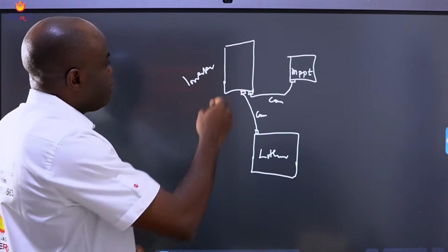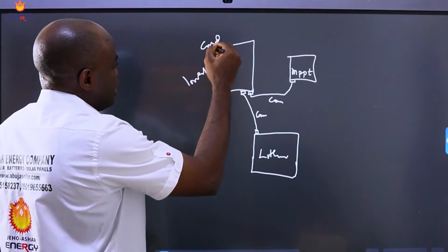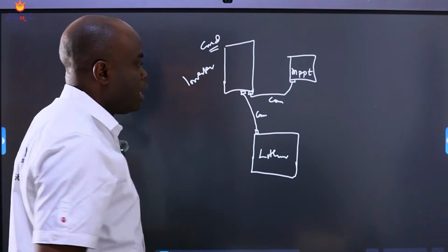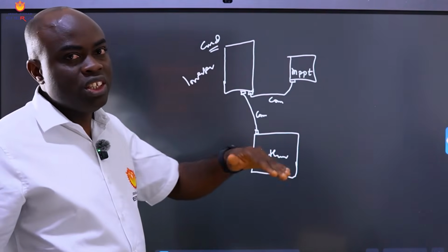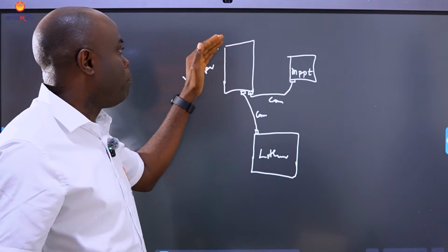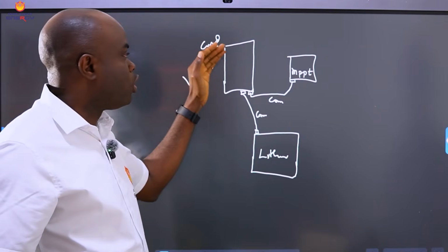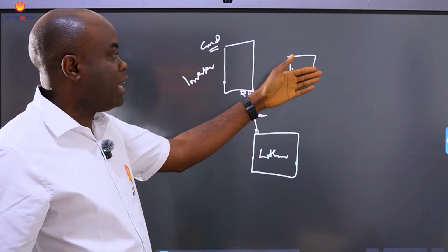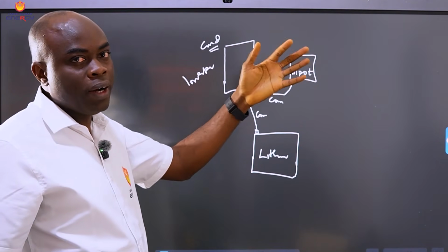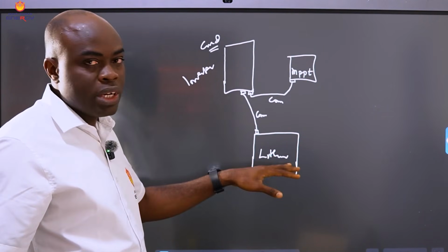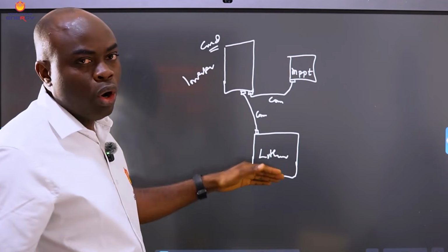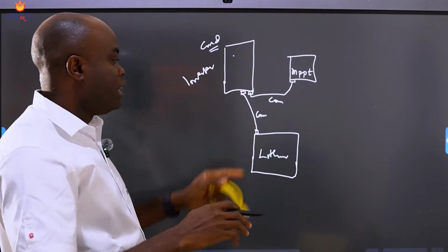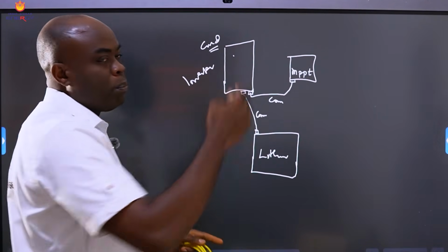And what happens here is this. For example, if this inverter has only grid, that is NEPA supply in Nigeria, and it has your solar, it can also help to manage the customer's power consumption when it comes to grid. In the sense that when you are in the daytime and there's a lot of sun power to harvest to charge your battery, and there is grid also, this inverter will not keep powering your load from grid and charging the battery when you have your panels.